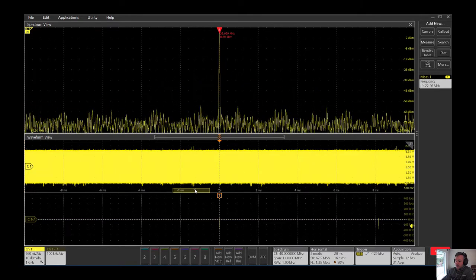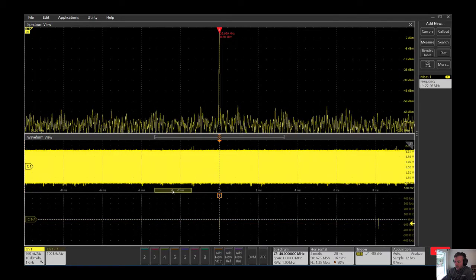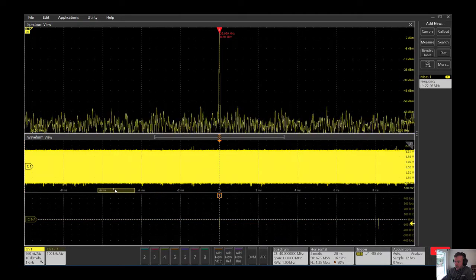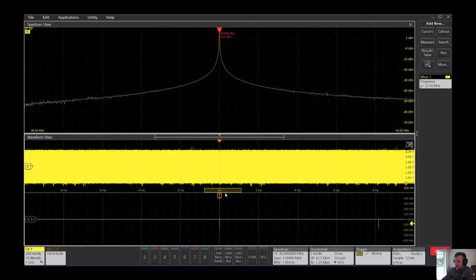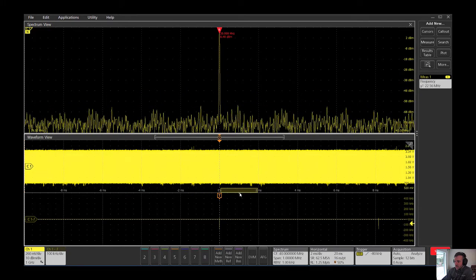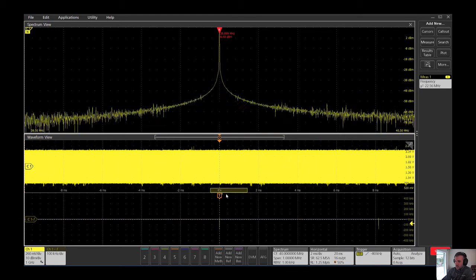So as I move it around, right here is where we had that clock jitter, or that clock dip below, right? It looks like it dips around 200 kilohertz below center frequency. But here I don't have that. So I have a nice, good, neat tone here. And then I get to my trigger condition, and that's where we start to see the clock have its issues, where it goes a couple hundred kilohertz below 40 megahertz.